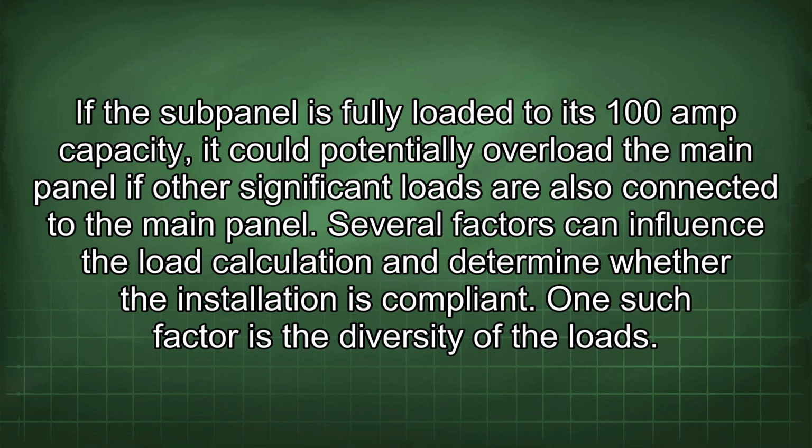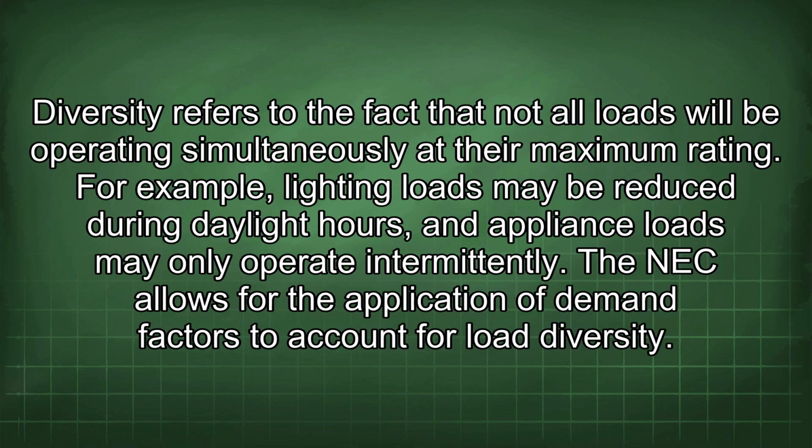Several factors can influence the load calculation and determine whether the installation is compliant. One such factor is the diversity of the loads. Diversity refers to the fact that not all loads will be operating simultaneously at their maximum rating. For example, lighting loads may be reduced during daylight hours, and appliance loads may only operate intermittently. The NEC allows for the application of demand factors to account for load diversity.